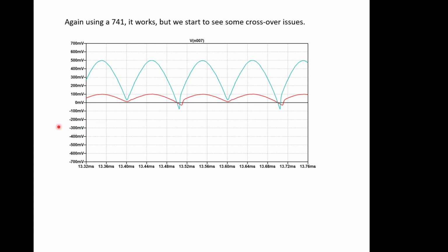Okay. So again, you can simulate that. And I've simulated it here with a 741, so I've put a sine wave in, and the output I'm getting now is a full wave rectified sine wave. Yeah, so the negative part of the sine wave has been flipped up and has come out here. This has been done for small signals, 100 millivolts, so we can see that it actually works for small signals and bigger signals as well.